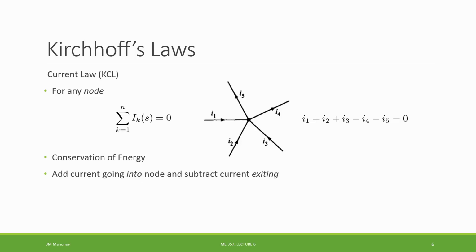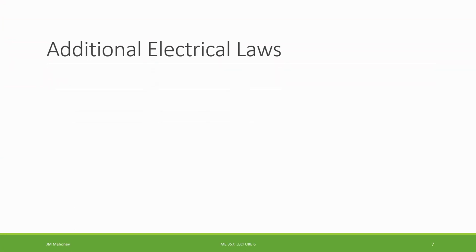And we have a couple of other ways of getting some equations that we're going to be using. We want to remember that in an electrical circuit, the voltage drop between two nodes is the same regardless of the path that we take between them. So voltage is not going to split from node A to node B. Current will split, and that will be important when we get to our more complicated circuits, especially when we integrate op amps a little bit later in this section.